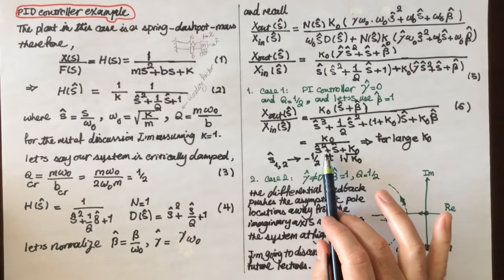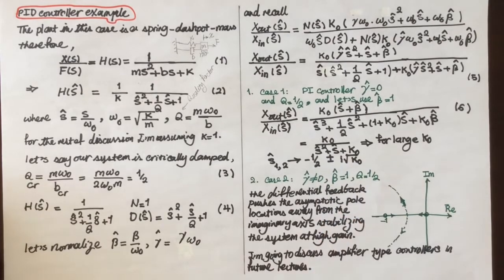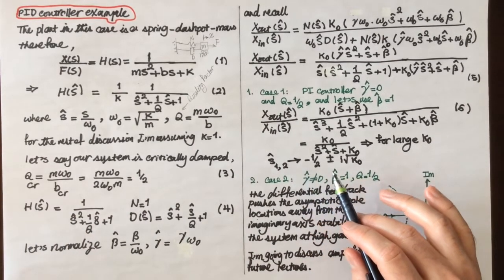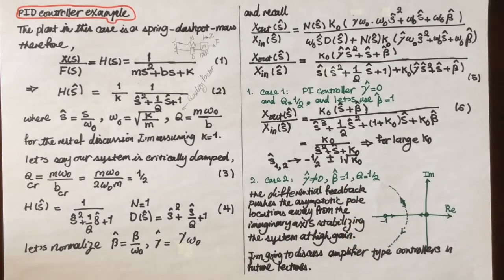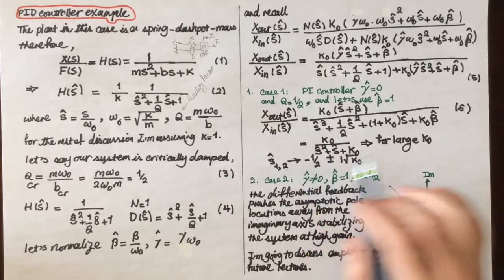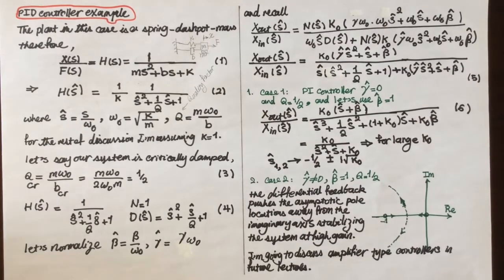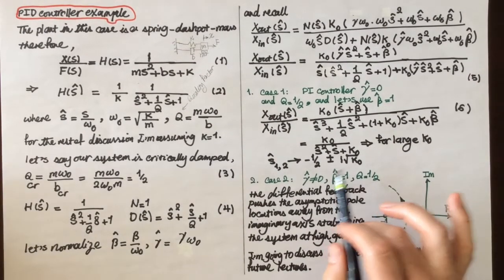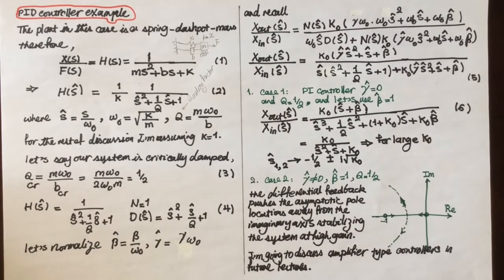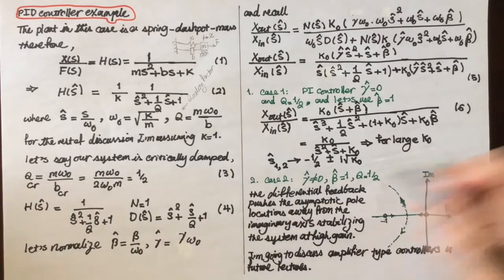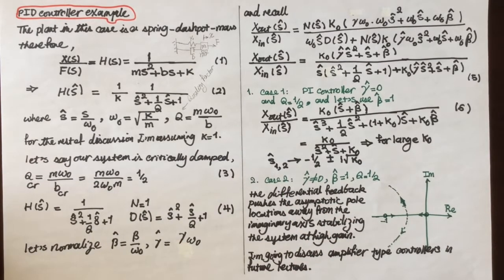If you pay attention here, going back to the root locus method, the method says that we are going to plot our poles, essentially drawing a parametric plot as k0 varies. So if you pay attention, these poles always have negative real part, so they are essentially stable.